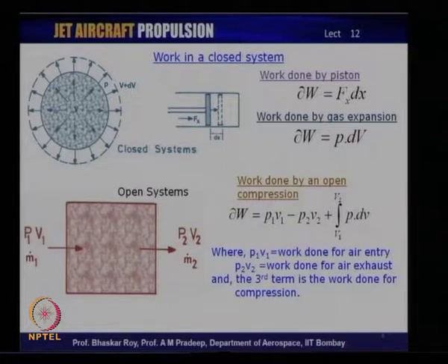Let us take a look at some of the fundamental issues. If we have a simple compressor in which you have, let us say, to begin with, a closed system, something which many people are familiar with. You have a closed system in which work is expected to be done either by a movement of a piston or by expansion of gases. It could be negative expansion, and the work done can be expressed in terms of the motion of the piston or the change of volume of the enclosed gas. Now, those expressions are written down there, and it shows that for a closed system, it is comparatively simple probably to write down the work that needs to be performed to do the process of compression.